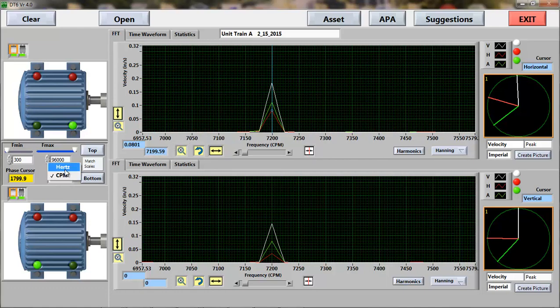Over here we can switch Hertz, CPM, or units. Again, that's our phase cursor. If I want to look at different plot points, here is our navigation, identical to the acquisition part, where I can navigate between two different units. These are the units. We can see that the units are phase synchronized because they're both green. And here's the data possible from those units.